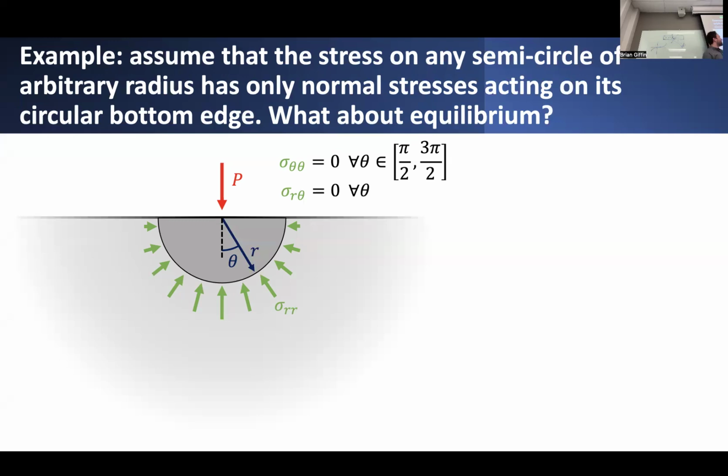You can replace that load by some equivalent loading. And as long as those two loads, let's say some concentrated load versus some distributed load, are statically equivalent, as long as the net force between those two different representations of effectively the same net load is the same, then far enough away from those loads, the solution fields will look basically the same. So it doesn't matter whether you're truly representing it as a point load or as a distributed load. Far enough away, it looks the same.